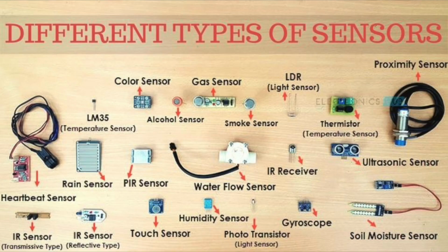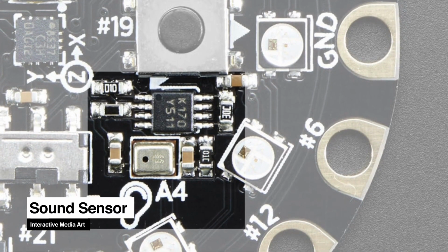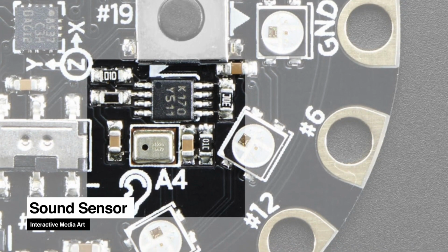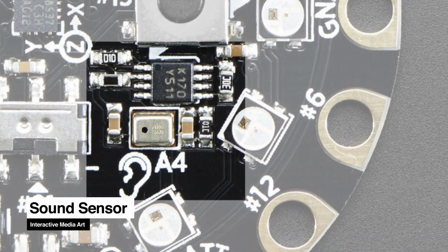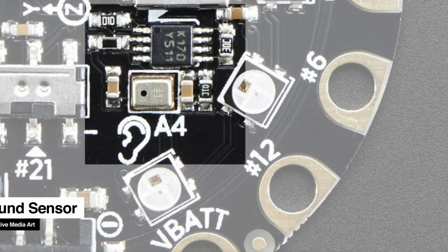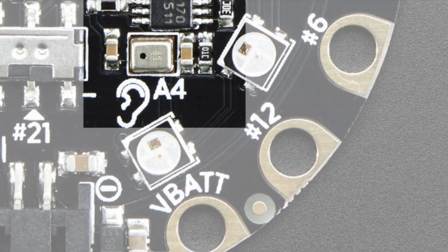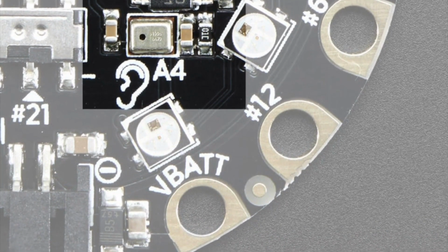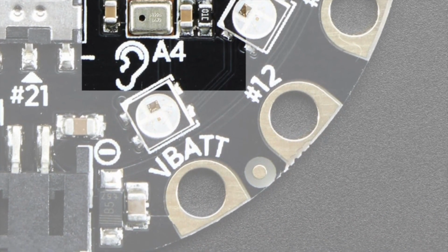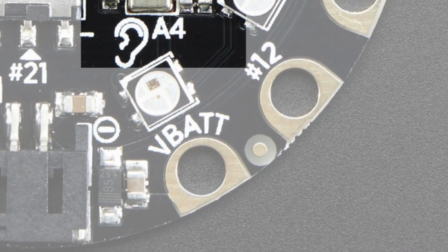Let's get started. The Circuit Playground comes with a thin MEMS microphone that can be used to detect audio levels. You can read the analog voltage on pin A4, but in most cases we're actually going to want to detect the sound pressure level, which is a pressure level that's taken over time. This will range from 50 decibels to 100 decibels in terms of if it's loud or if it's quiet.